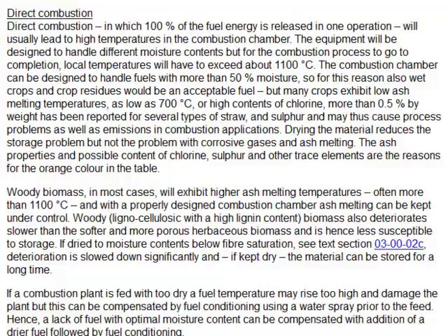So woody biomass will generally have a high ash melting point, and that renders it very suitable for direct combustion. The dimensioning and the design of the combustion chamber can also be such as to accommodate molten ash. This is only a question of designing and dimensioning the combustion chamber.